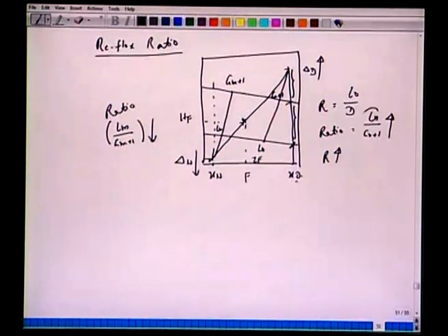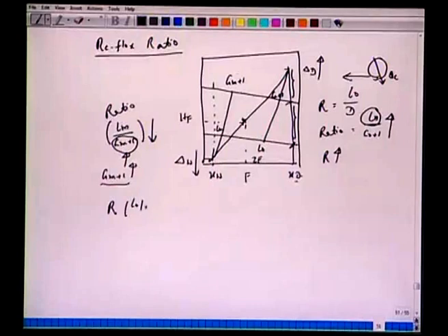So, the load Ln on the condenser increases, we are taking larger reflux here. So, the load QC increases here. Now, if this ratio increases, this ratio is decreasing, you can see that Gm plus 1 increases. That means the vapor load on the reboiler also increases, right. So, all it means, we can write here that if the reflux ratio R, L0 by D, increases, QC as well as QB will increase.